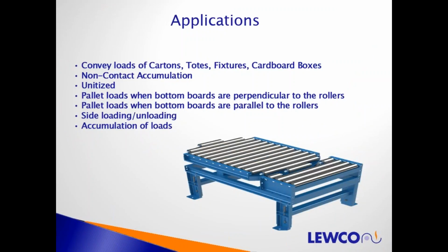Some different applications that you can use turntables in are to convey loads of cartons, totes, fixtures, or cardboard boxes, non-contact accumulation, unitized loads, pallet loads when the bottom boards are perpendicular to the rollers. We would use a roller conveyor in that application, or pallet loads when bottom boards are parallel to the rollers, where we would use chain conveyor. Side loading or unloading, accumulation of loads.